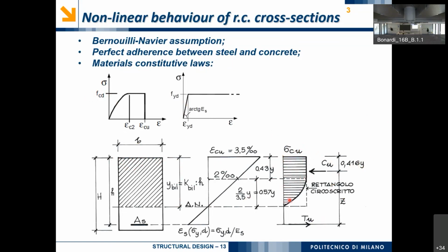And then we have on the other side just the contribution of the steel, because as we have said during the last lecture, concrete does not resist tensile stresses. That's the reason why we put reinforcement bars, which will provide this ultimate force in tension.